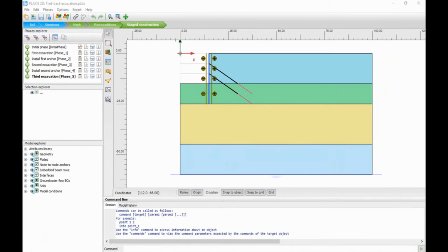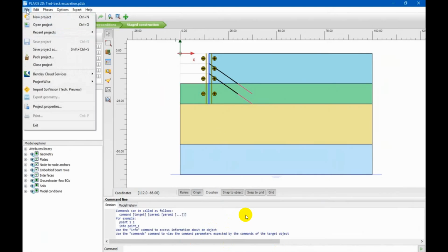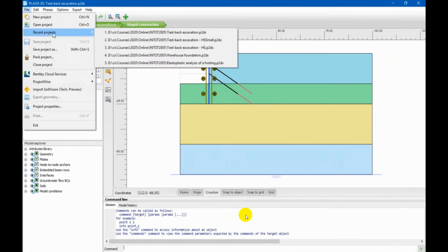You can imagine if you would make more than 4 layers, thinner layers, and more of them, you get more accuracy if you do so. For this exercise, only 4 was used. The deepest layer is very stiff, so that is the lightest blue at the bottom. It's very stiff because we assume that there is very little going on. Instead of the Mohr-Coulomb layers, we asked you to do for today's homework assignment to use it with the HS small model.